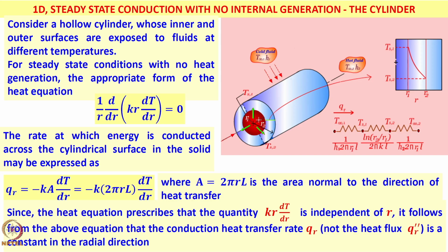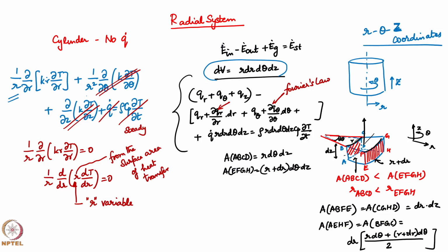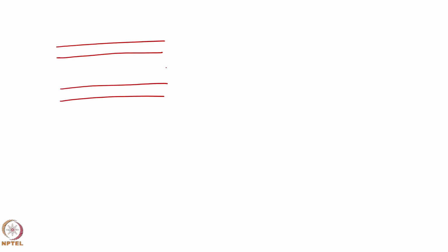This is a classic case of hot fluid being transported through the pipe. Wall has a particular thickness. So, the inside wall is hotter, the outside wall which is exposed to ambient air could be cooler. So, we are looking at a typical one dimensional radial heat conduction problem, where if I just draw this pipe like this for you, I am just taking a cut section somewhere.